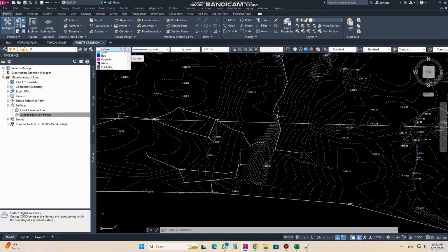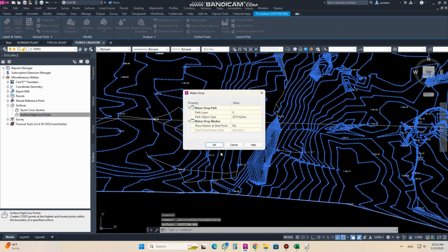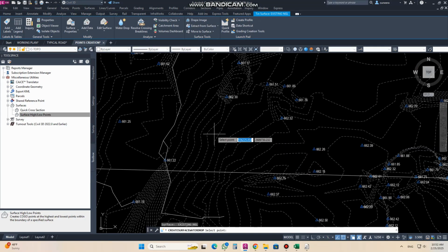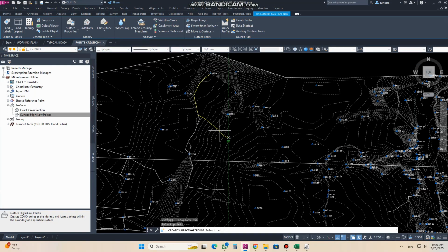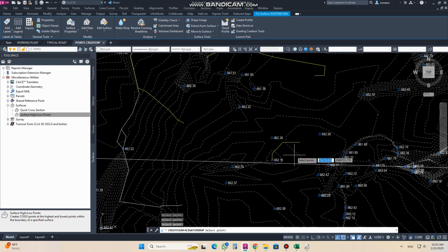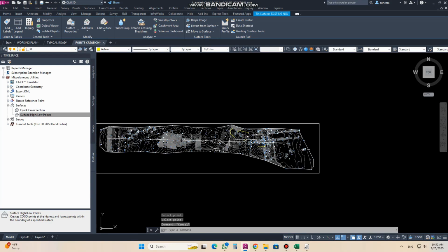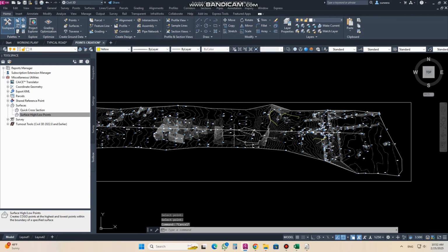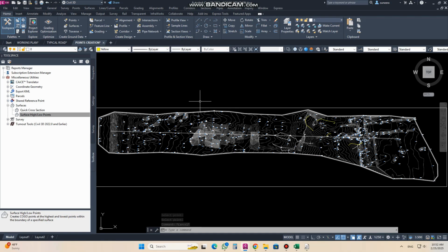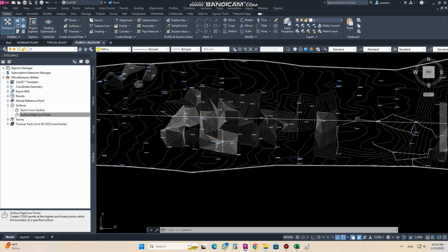I changed it, let's take the yellow line, this one, and when I create any line here, it will connect to the lowest point here. Now you can see it connects to the lowest point here, and it connects to the lowest point here. So from anywhere this point is connecting to the lowest point. So like this you can create the high and low points inside your plan where you need. Sometimes we need this for creating a manhole like this. So this is the method